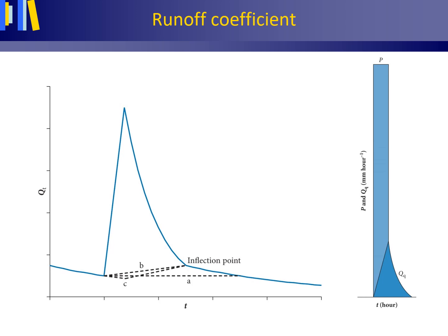As often runoff coefficients on a storm basis are surprisingly low, as interception and evaporation losses and storages at the surface and in the subsurface usually are quite high. However, in situations when a small clayey drainage basin is pre-wetted by earlier precipitation, or when rain falls on a frozen soil, or when snow melts, storms with a high runoff coefficient may occur.